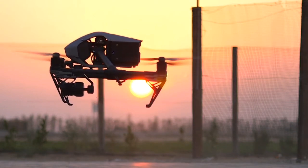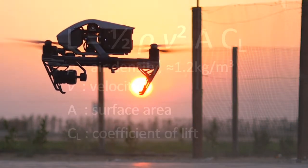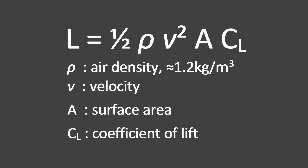The formula for calculating lift is given as 1/2 the density of air, shown as ρ, times the velocity v squared, times the surface area A of the blade, times the coefficient of lift c subscript L, which is based on the blade's surface area and an angle of attack. The only value that a drone will ultimately have control over is the velocity, as it rotates its blades.